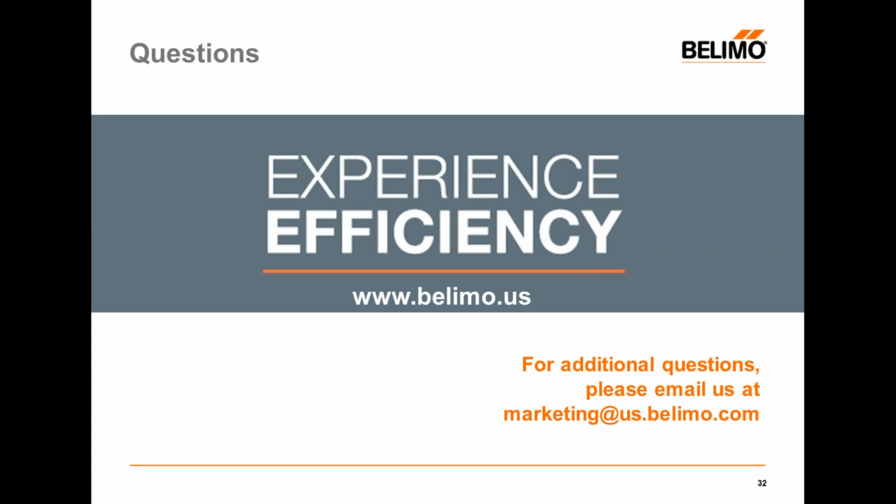Okay. Next question. What is the most common smoke control strategy in a healthcare facility that is considered a high building? And this is in Canada. Considered a high building, is it meaning a high-rise building? If that is the case, generally what I see most commonly is fire smoke dampers interlocked with the starters on large air handlers. So as the duct detectors in the areas being served by the air handler sense smoke, they break the contactor that controls the fan, or the contactor on the VFD controlling the fan, and that in turn shuts all the fire smoke dampers closed in that application.